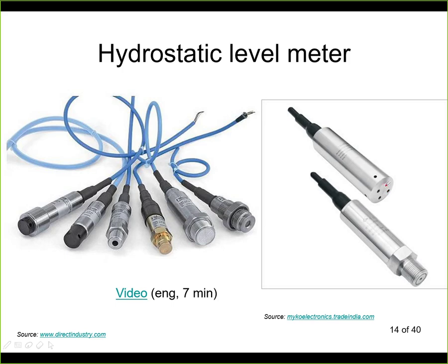Those holes allow the liquid to enter, they prevent larger particles from getting into the sensor, and then there will be a diaphragm and the sensing electronics. Of course, all this will be made waterproof, so it will work when it's submerged in the liquid. And then we see a long cable, and with this cable it will be connected to the second unit, where we actually will have the display, or will have some transmitter for the current signal that we need to connect to a controller system, for example.